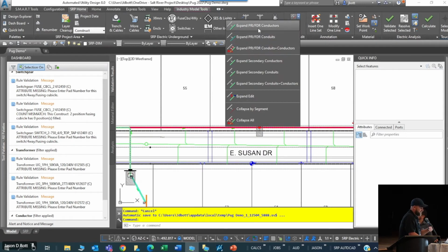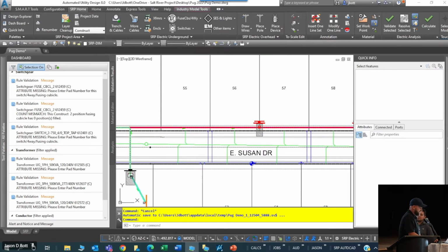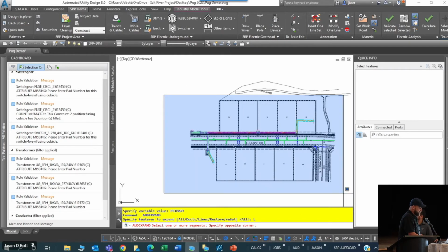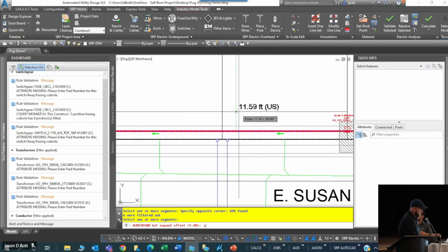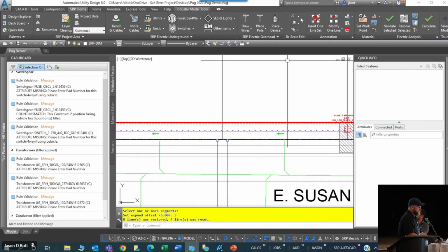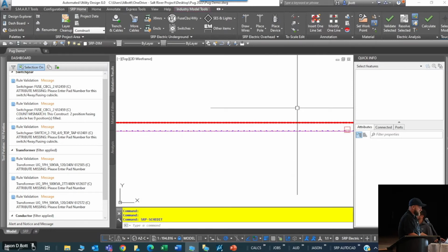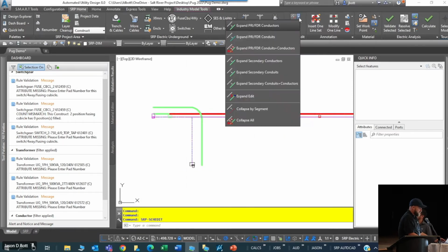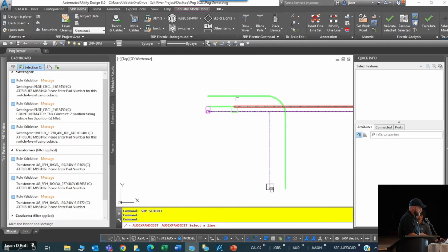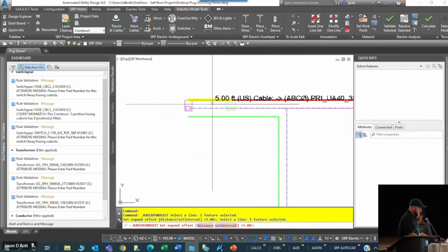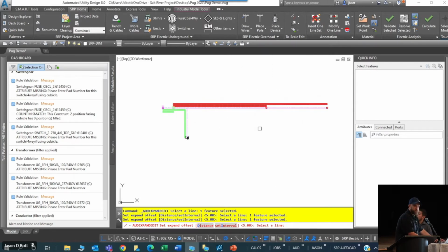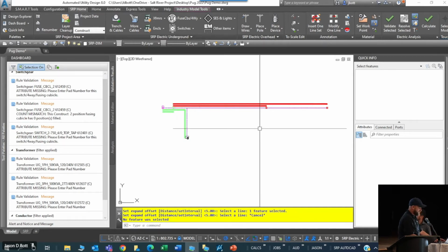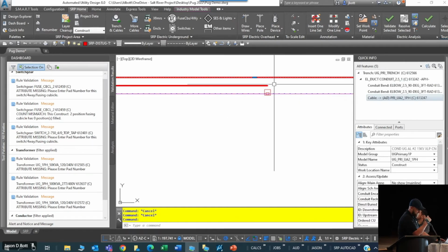So we have expand primary. What the users do is they kind of look at what the schematic's going to look like. So if I want to see what this looks like, I can select the whole thing. It filters out only the primary. I can set how far I want it away. So in this example, I want to say 5 feet, and it pulls all the primary cables out. I'll turn off. We also have a layer toggle in here. So it'll turn off the background to let the user see what's kind of going on. There's expand edit in here where I can move these around. So for example, I can say, well, I want this down here. Say I want this over here, and I got 2 primary lines here, and I can visually look at that, and it's all built on top of each other. It's still associated, so users will use it to actually select it in there if there's a big list.